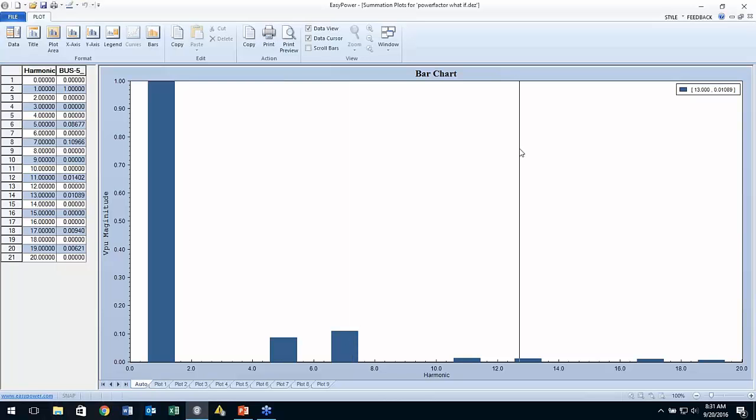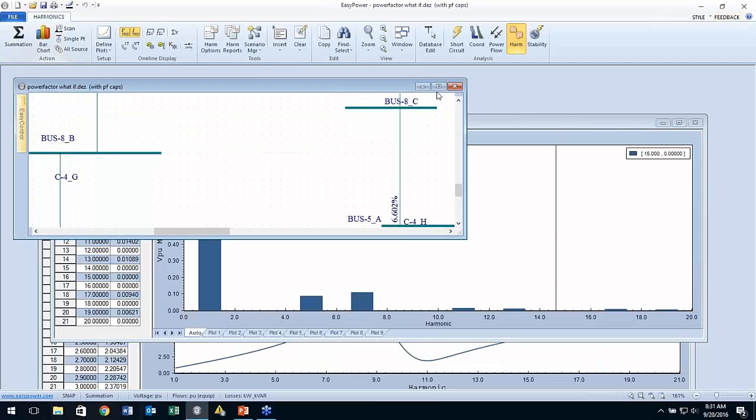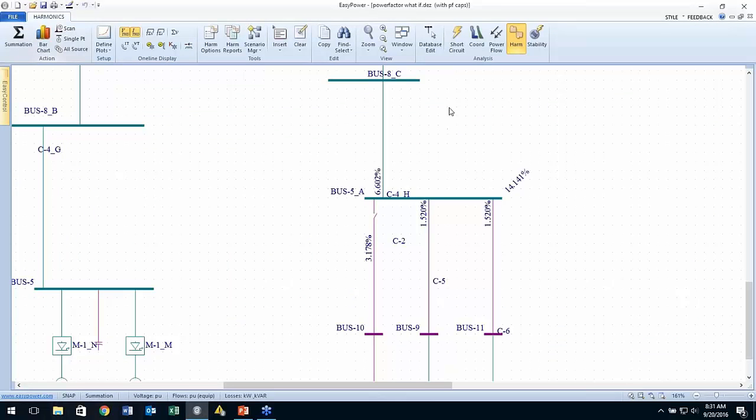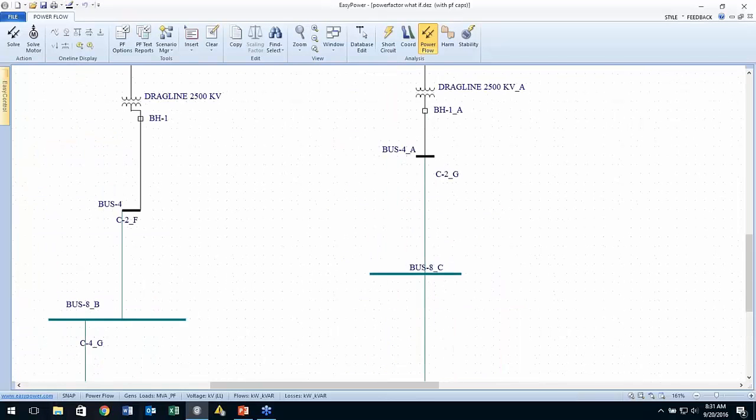So I guess bottom line is I'd have some serious issues just throwing that much capacitance in if I had this type of harmonic content in my system. It also brings back the questions like, and this gets a little bit fun, what happens to my power factor? Do I need all that capacitance now that I'm using the VFDs?